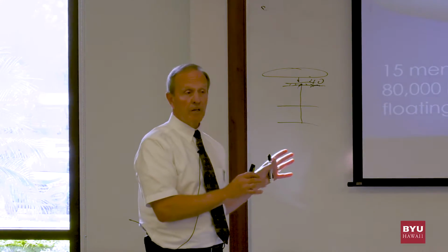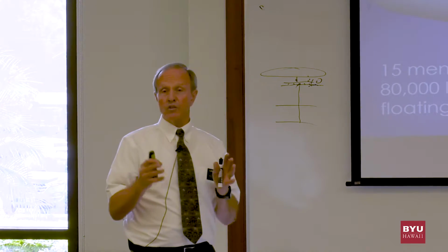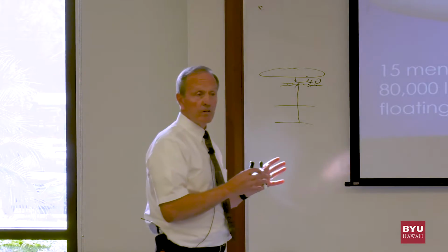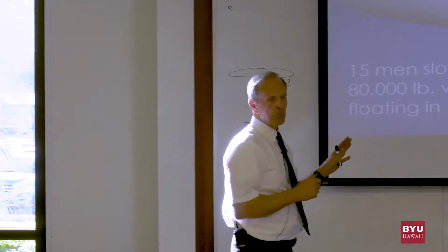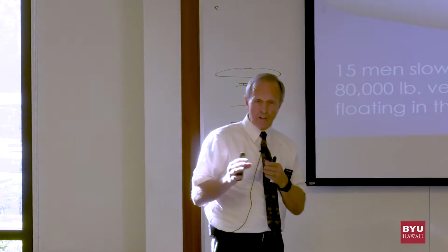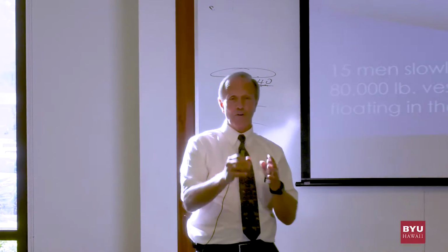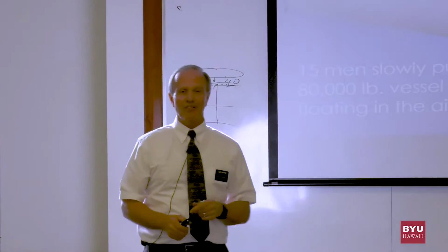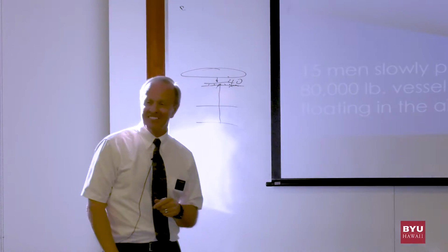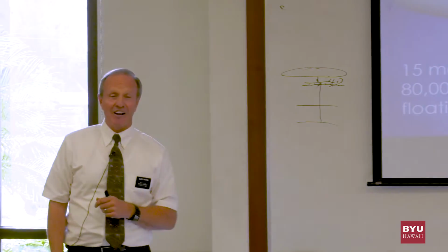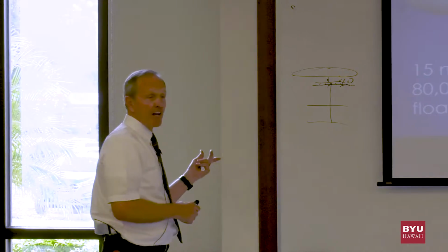We pulled the brand new one in, made another pick, took the shoes off of the old one, welded them onto the new one, and then put those airbags on again and walked that great big vessel right back where it was. Turned off the air, we're done. So anyway, there are some fun things out there, you guys, that's really neat. That's called thinking out of the box.